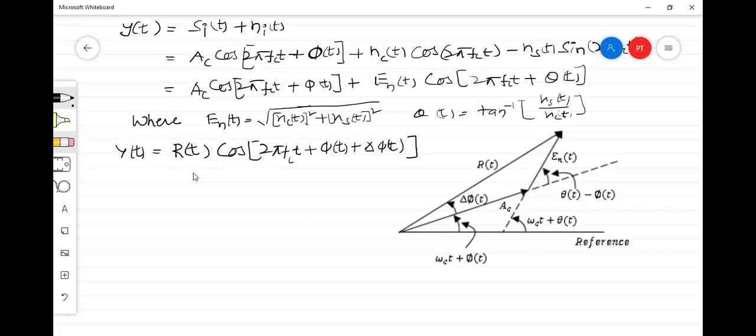Why is an FM system inherently immune to noise? Because of this amplitude limiter, which will remove the amplitude variations of an FM signal that are created due to noise or other factors. That's why we are least bothered about r(t). Then what is the important factor that worries us? The angle variations due to the noise. So let us find out what its value is.